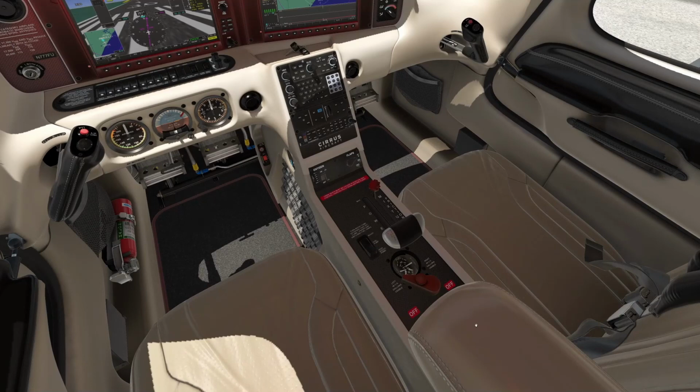So fuel pump, should hold prime, middle, okay, so the fuel pump is working right. Then a clockwise turn of the fuel selector should, good, counterclockwise, yep, good. Now if your fuel selector is out of sync with where it should be, you just have to turn it all the way to the one side or the other to get it back. And then the flaps should only go down one notch. And it is. All right, so everything is working the way it should.